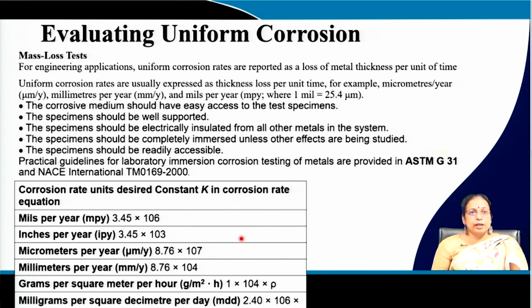Now, as I said, aqueous corrosion may broadly be classified into 8 categories. The first, very simple category of corrosion is uniform corrosion, or you can say environmental corrosion, where corrosion is uniform all throughout the surface.